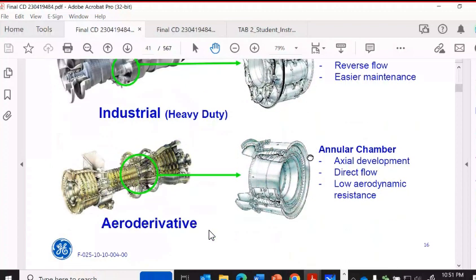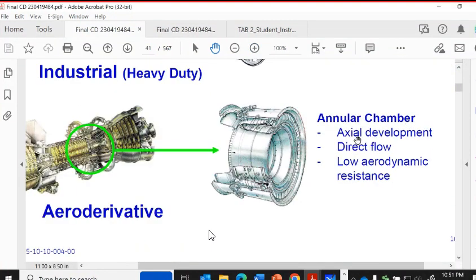What you have is, as explained earlier, an annular combustor. If you notice on here, it's got the same shape as the can combustor, but instead of being individual cans, this is just like one great big can. And so on your application, instead of being limited, like if you had 8 combustor cans or 10 combustor cans, to 8 or 10 fuel nozzles, you have 30 fuel nozzles.